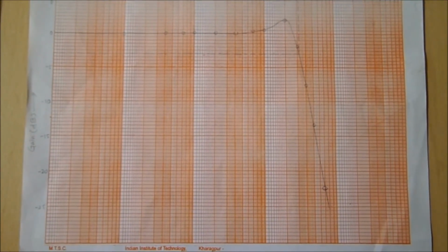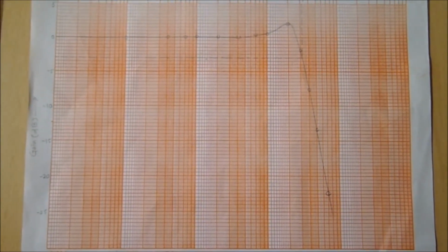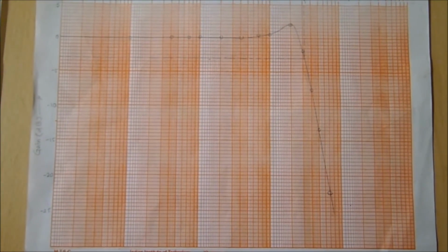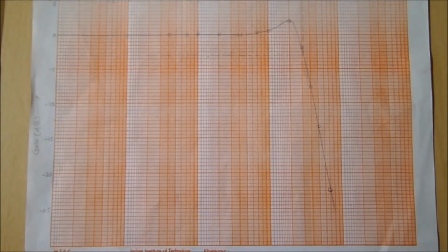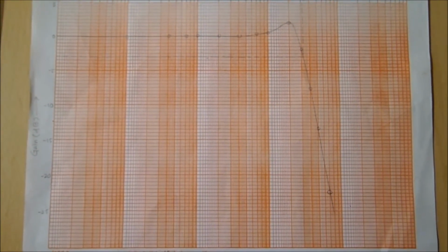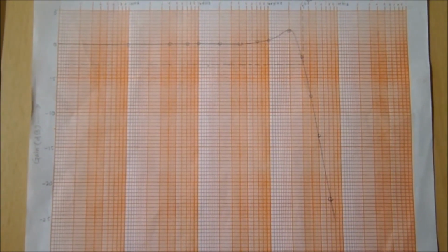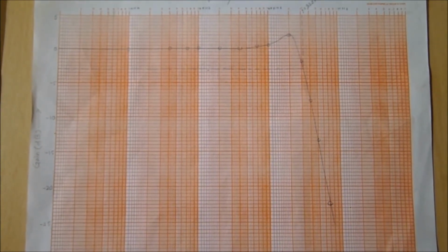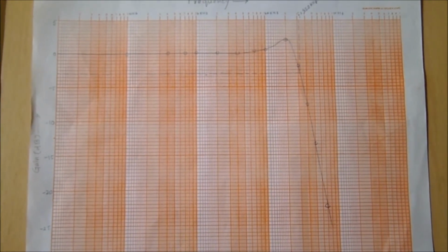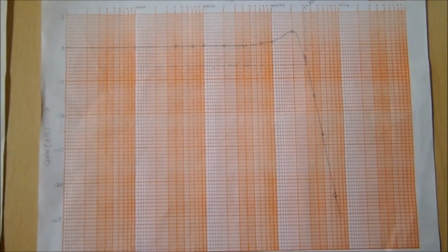This is the Bode magnitude plot for the circuit. As you can see, this configuration gave us a constant gain of 0 dB up to a frequency of about 100 kHz and then showed an overshoot before falling off at nearly 40 dB per decade. The overshoot is obtained because of the presence of conjugate complex poles at that frequency. The system has complex poles because it is an underdamped system, as was clear from the step response.